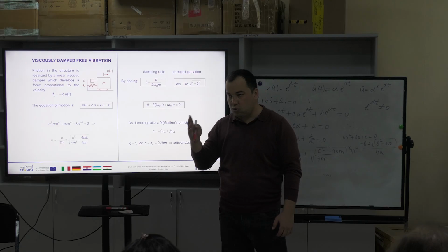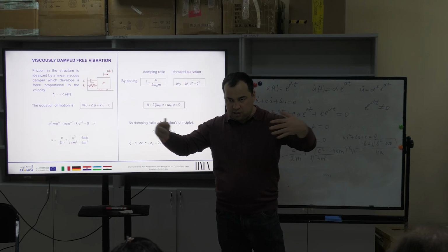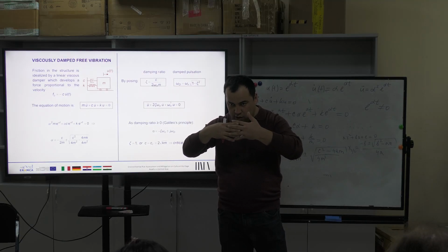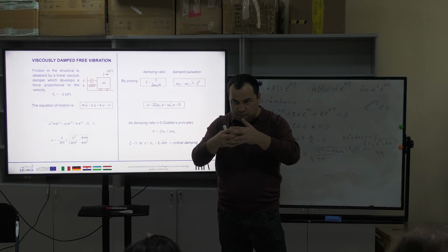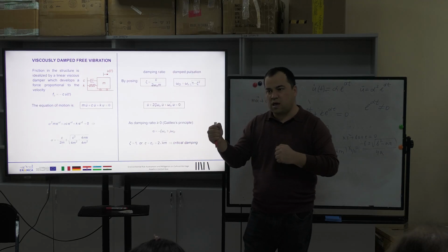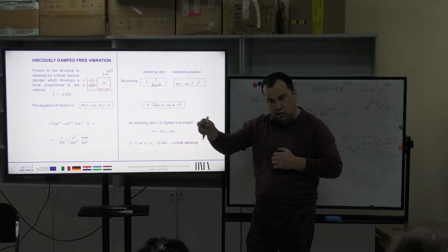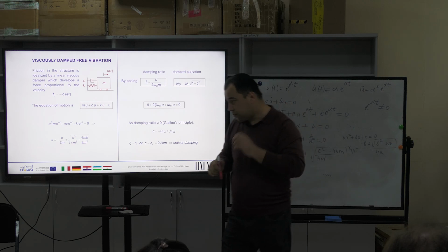That friction keeps absorbing it. If you have brick construction, the bricks will rub against each other and keep absorbing the signal. There will be damping. If you have something like resin or some viscous hydraulic cylinders inside the building, those also help the building resist.